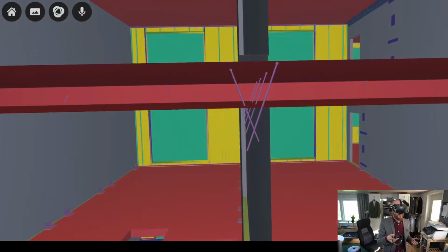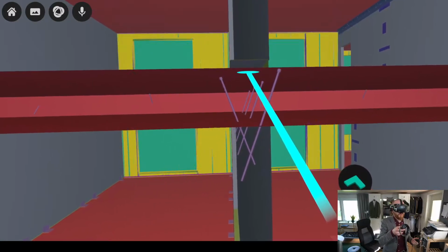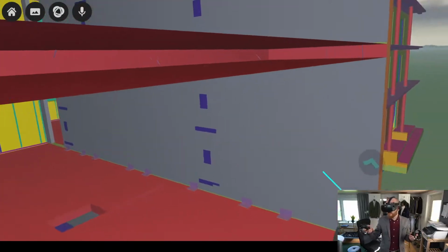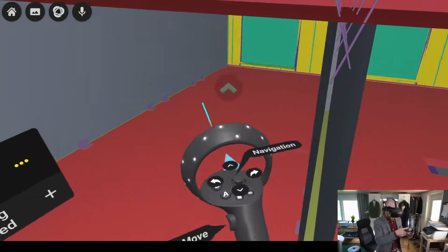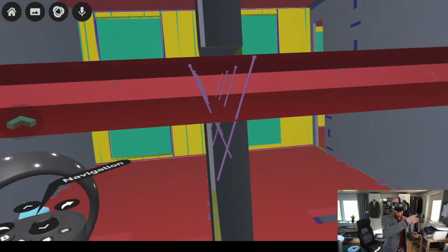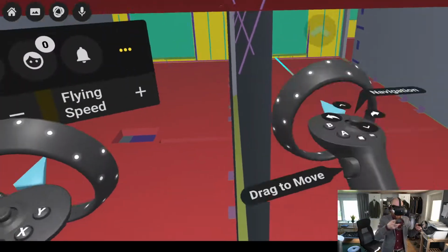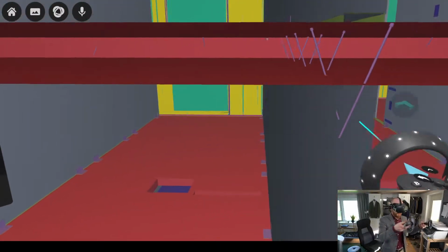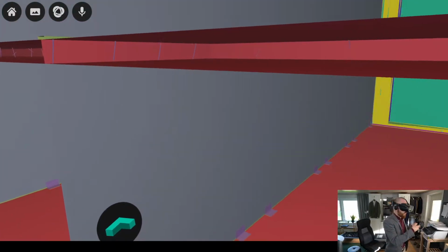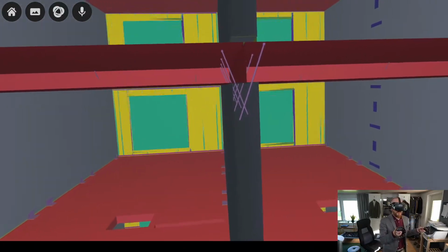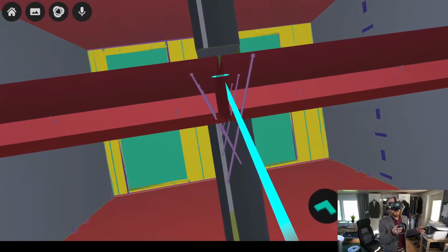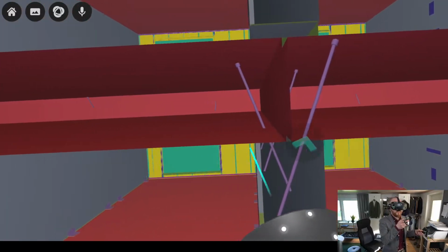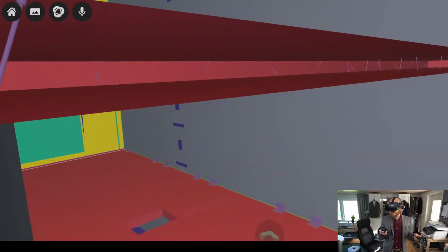And you can have either this case here with the floor slabs that are continuous. So this way it spans over, here's one dwelling and here's another. So the CLT slabs span over several. This is an apartment separating wall and you got a floor slab that goes over two apartments. And then you have the second case here is that you align so that there's a separation, and here comes the next CLT element. So there's a little slice in between them. And this is very important.